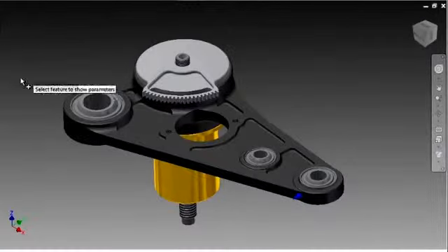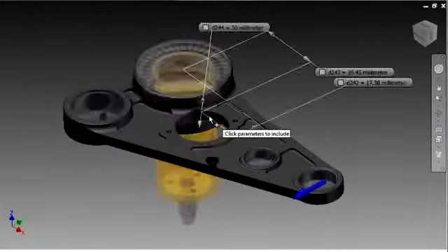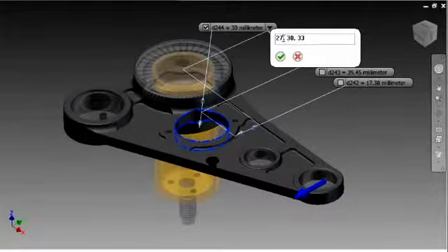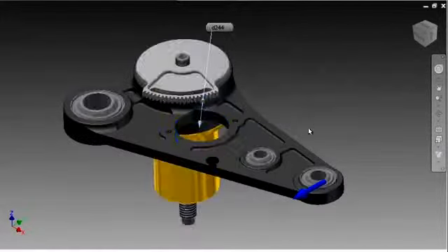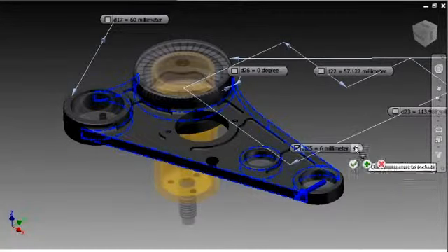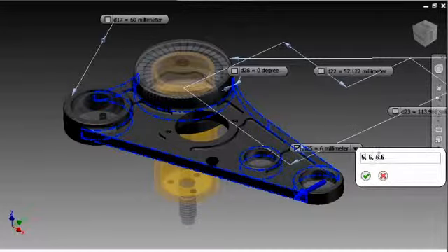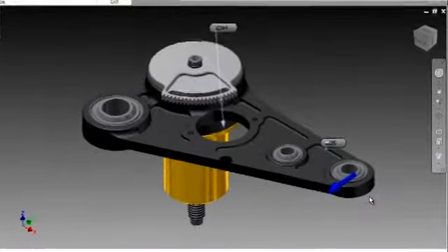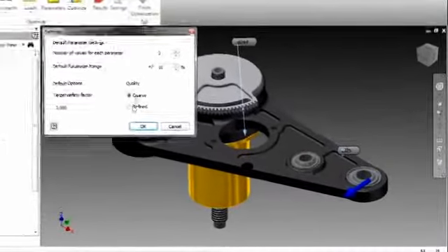Next, we will use the same design parameters that Inventor uses to store the dimensional values for part features. However, we are going to use Autodesk 360 optimization to specify a set of alternate values for each of the parameters selected, which, when combined, will define a range of feature and part sizes. From this range of values, the optimization service will essentially build iterations of the assembly and then test them against the target factor of safety that we will set here.